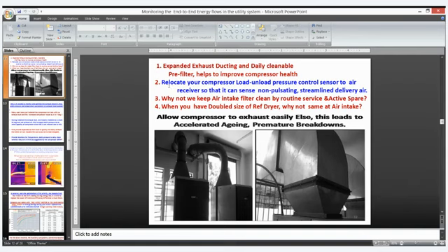The high cost option, you can discuss with your OEM. If we are able to double the air compressor's air intake filter, definitely it can withstand for a longer time, and the Pascal drop across the filter will be less, and definitely the flow will be rated to the maximum delivered flow. It will be almost 100%, even after say 3 months, with condition monitoring. So both aspects are there.